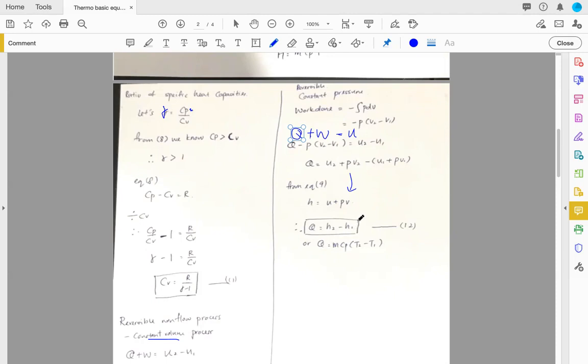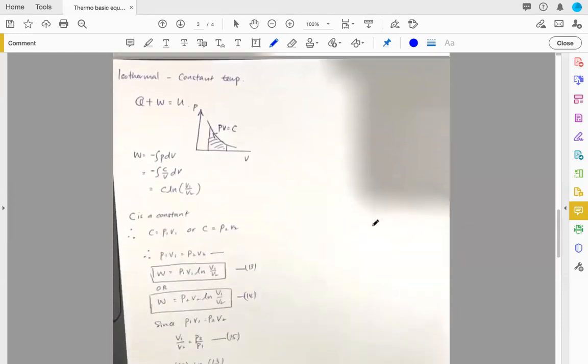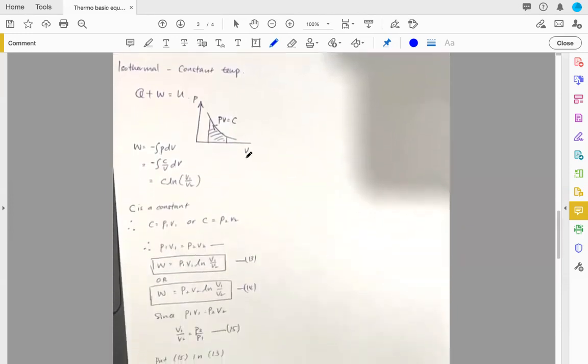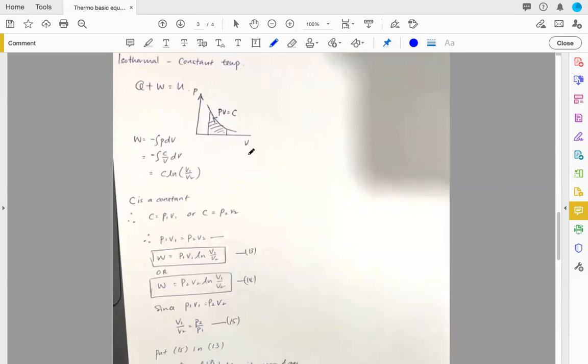That is very good. It means we can refer to the thermodynamic table, for example at a certain pressure, and then you can enter the temperature, and you can get your H1, H2 minus H1, and you can solve the problem. So let's move to something a bit more complicated. Maybe you learned this before, I'm not sure, but this is definitely useful for the next few chapters.